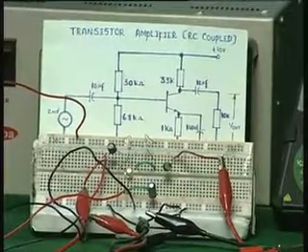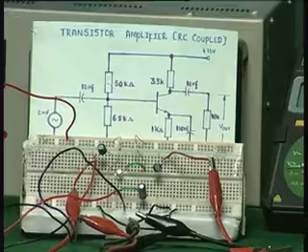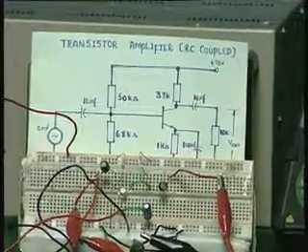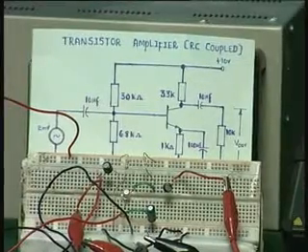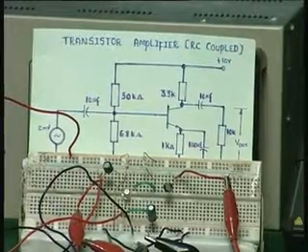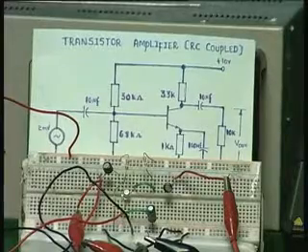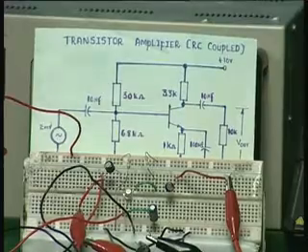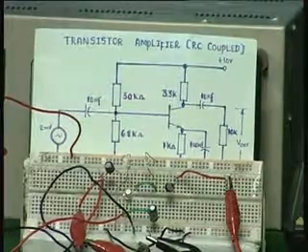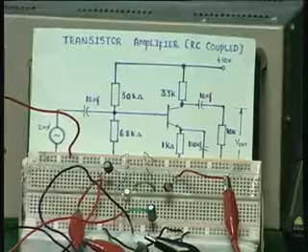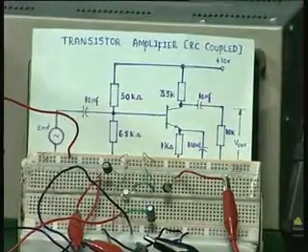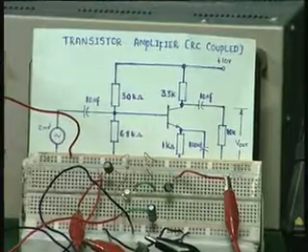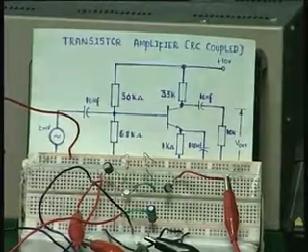Now if you want larger amplification, you can go for one more of this and couple this to the base of the next amplifier, and still you can have further amplification. So one can cascade different amplifiers and get very large gains by having multi-stage amplifiers. So we will see some of the basic theory and the models behind the transistors, and then the construction of multi-stage amplifiers, etc., in the next lecture.